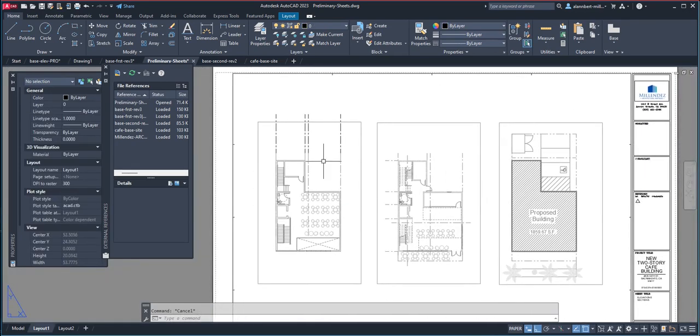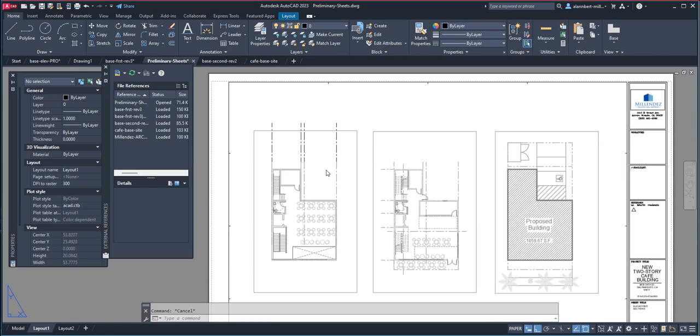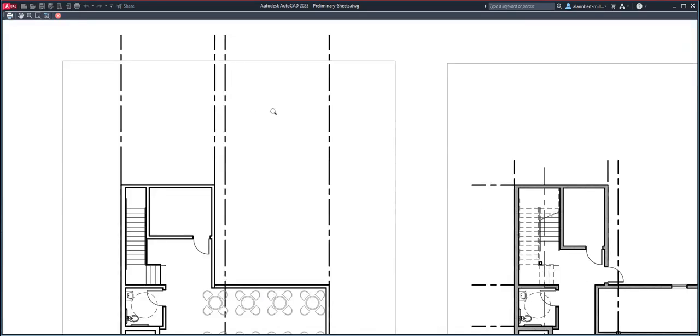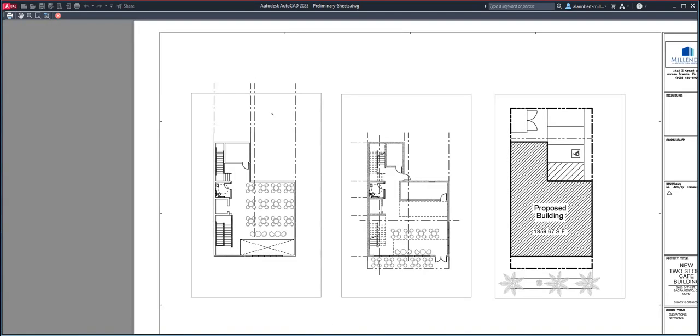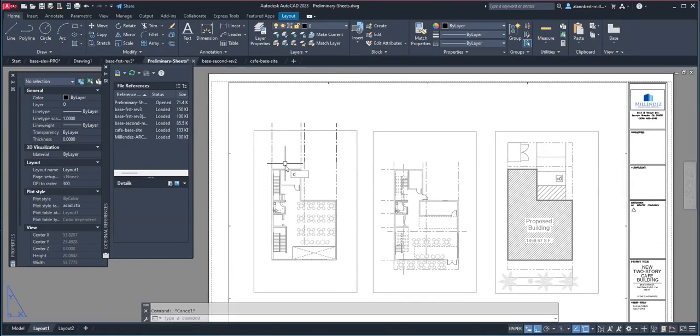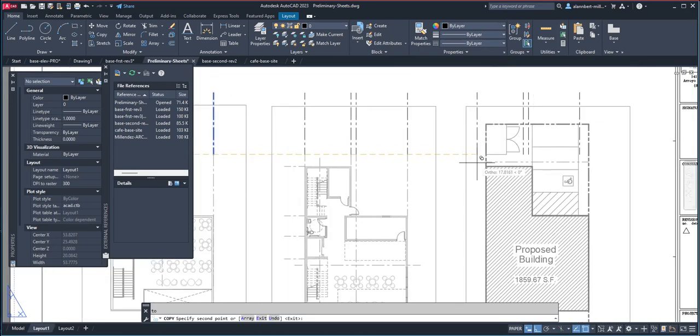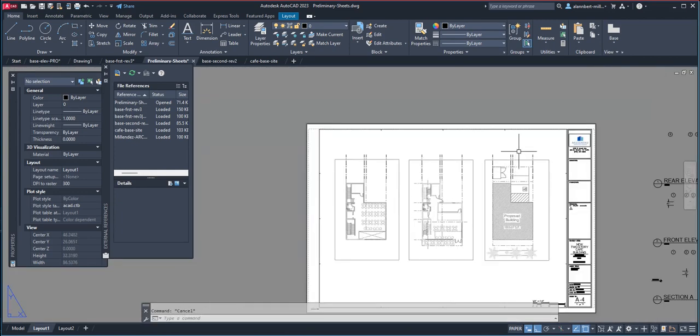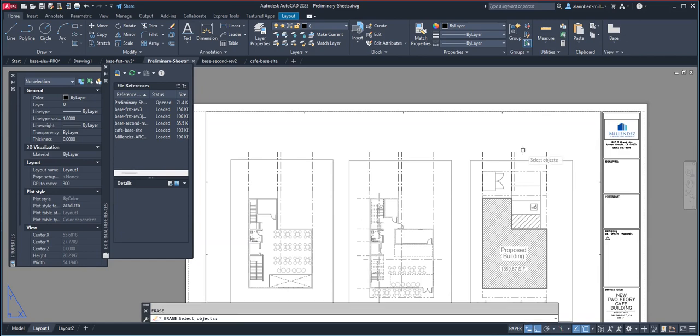And then double check on the preview if they seem to look seamless. They do. And then now all I have to do is copy that whole set from here to here. And you actually want to copy that one also to your site plan, but on a site plan, you don't copy the in-between grids.